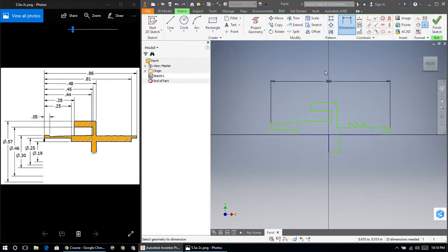I want this dimension line to be further away, so I'm going to press escape a couple times, and I can click and drag it up here higher, where it's out of the way, because I'm going to start adding a bunch of small short dimensions, and we're going to start everything on this left edge and work our way across. The only thing we're not going to dimension from the left edge are the 3 nubs here. We're going to do those differently because they don't show up with any of the dimensions that came from Project Lead the Way.